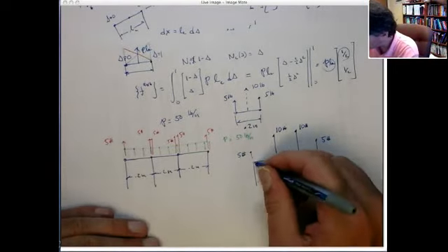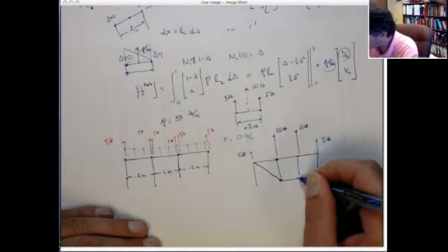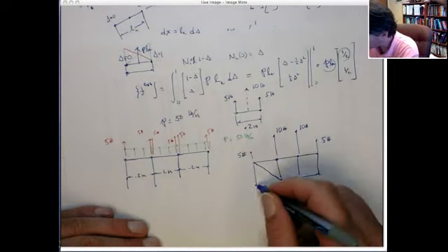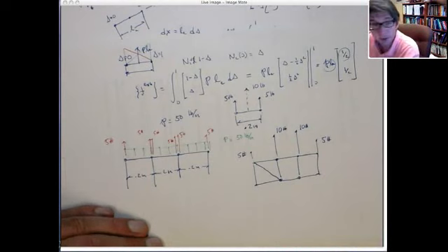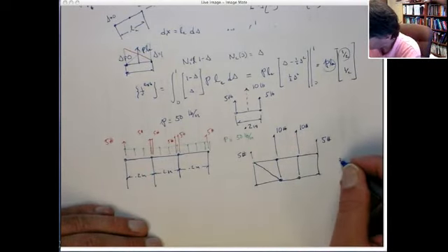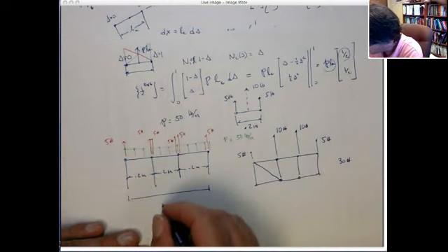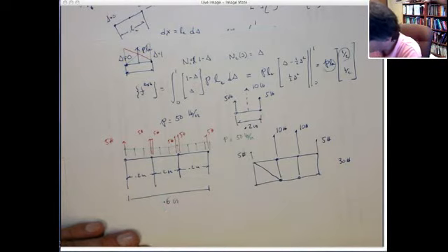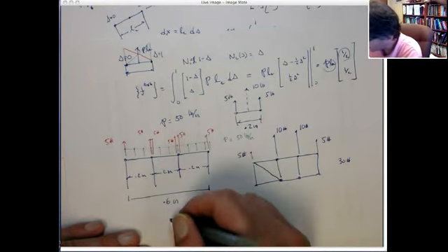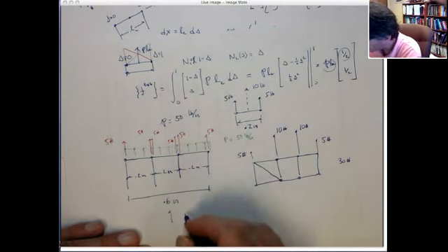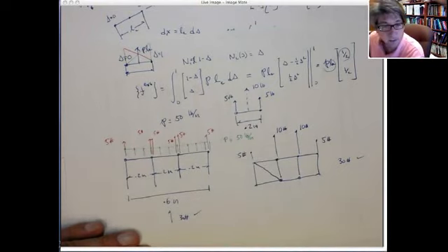And again, this is whether there's constant strain triangles or Q4s. That's what you would put on the edge. Now note the total force here is 30 pounds. This distance here is 0.6 inches. And so 0.6 times 50, the total force acting on this whole edge is also 30 pounds. So these numbers match as you would expect that they would, all right?